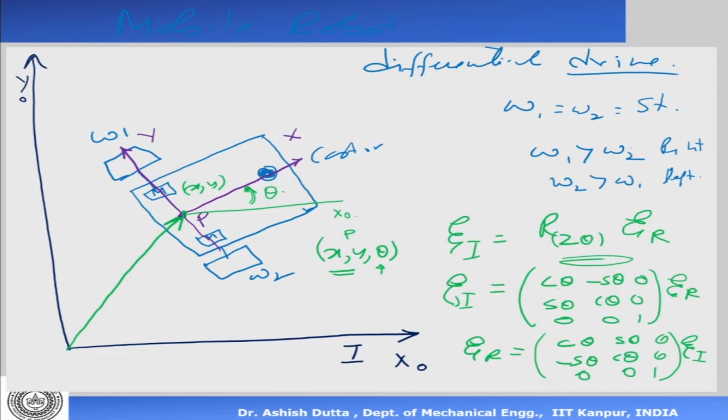So today we looked at homogeneous transformation matrices. Then we looked at how to find forward kinematics, inverse kinematics, and then further we went on to look at the question of singularities, and I explained the importance of looking at energy, minimizing energy, in terms of performing a task, finding a path in robot motion planning.